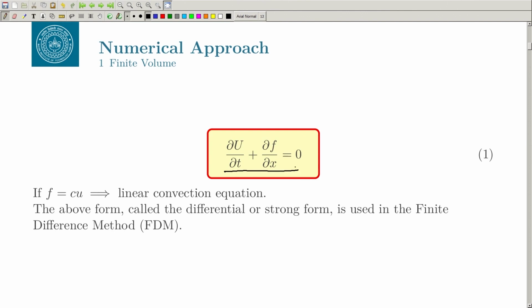It can be a convection equation where F equals just c U. It can be a diffusion equation where you are putting the gradients inside this function F, so F equals maybe k dT by dx or something like that. As we have seen, it can also represent the 1D Navier-Stokes equation, where F can be F_i plus F_v, the inviscid part and the viscous part.